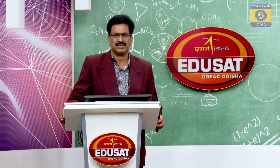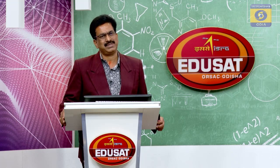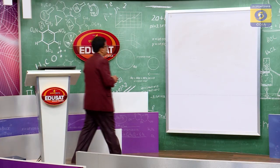Now we are going to discuss one of the most interesting topics, which you use in day-to-day life: the grouping of the cells. I said earlier what a cell is and what it provides. It provides EMF and potential difference. The EMF is there when the circuit is open, and the potential difference is there when we use that cell to close the circuit. Now we are going to discuss the grouping of the cells.